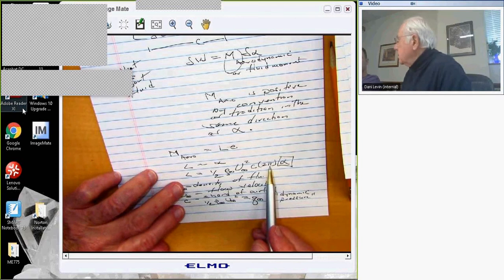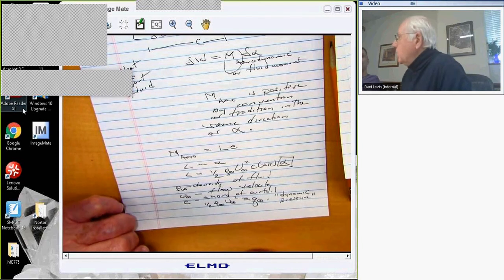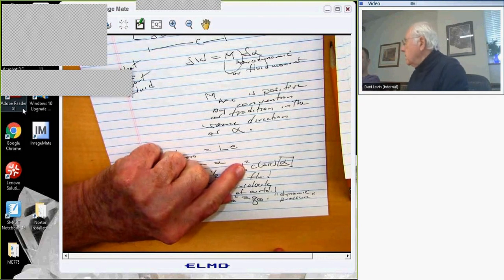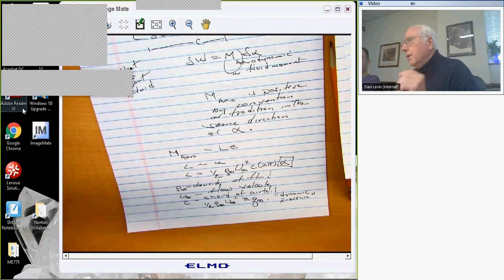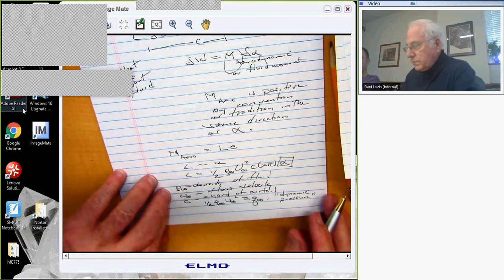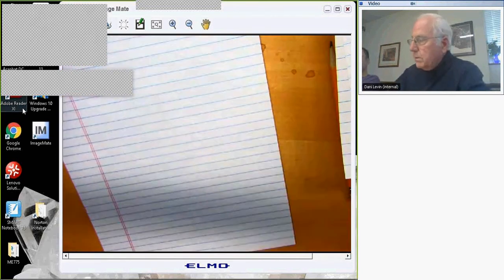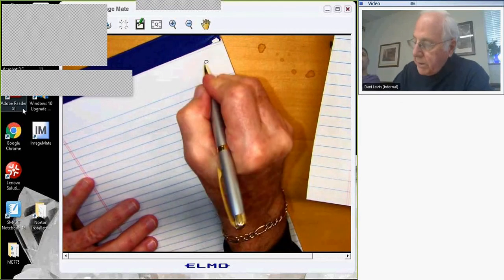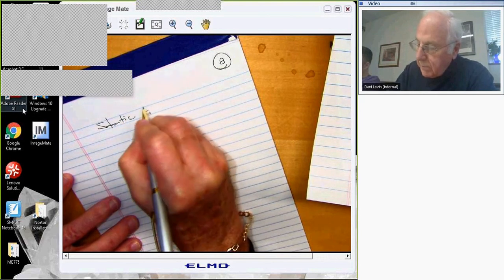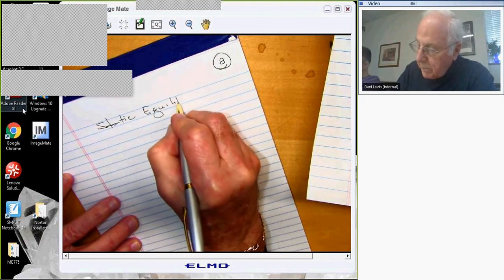And it turns out to be, it's not quite 2 pi, that's sort of an idealized number. It's a little less than 2 pi typically, but you know, it's 5.7. It's not 6.28, but hey, close enough. Right? On the other hand, if you're the Wright brothers, you really want to know it's 5.7 rather than 6.28. But the theory that we'll go through later says it's 2 pi. Okay, so with all of this, we can go back and determine an equation of static equilibrium for our simple model.